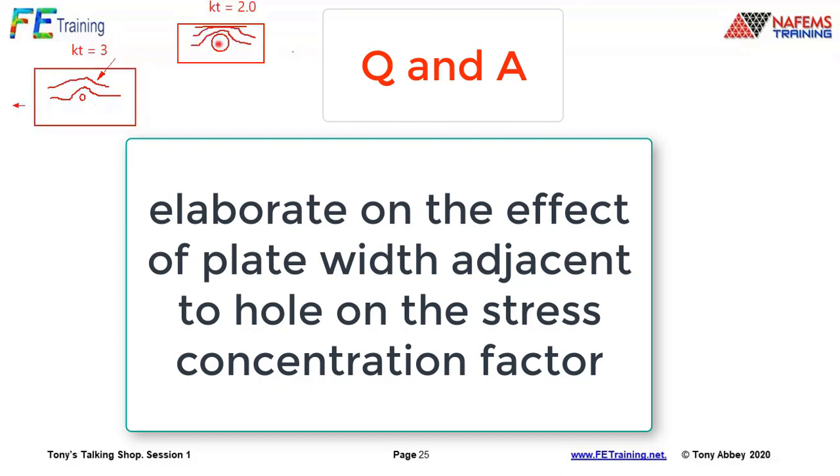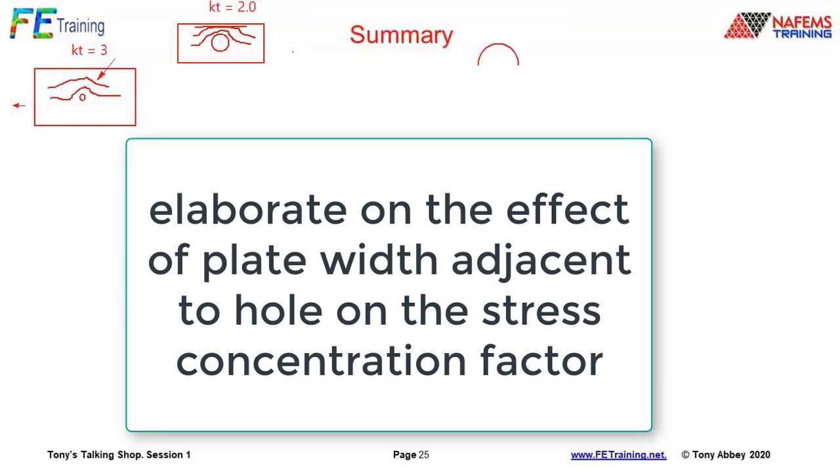So our effective stress concentration factor is dropping, and in the limit, if we only had a tiny little distance away from the hole, which is like here, and we put an edge right on here, then surprisingly, the stress concentration factor would go right down, because we're pretty well forcing the stress to flow down that ligament almost like an even flow.